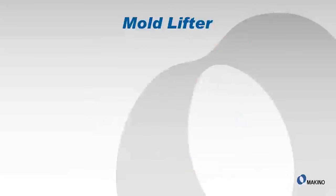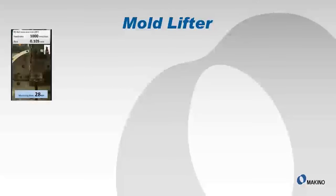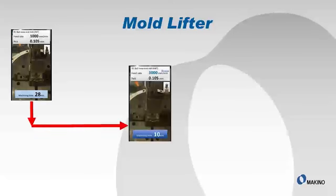On the second group of mold lifter parts, top side, I did the same thing here. You're looking at the first approach, 1,000 millimeters a minute, about a 28-minute cycle time. The second one, we got 3 times the feed rate on a 6-flute end mill, so we're at 3,000 millimeters a minute.